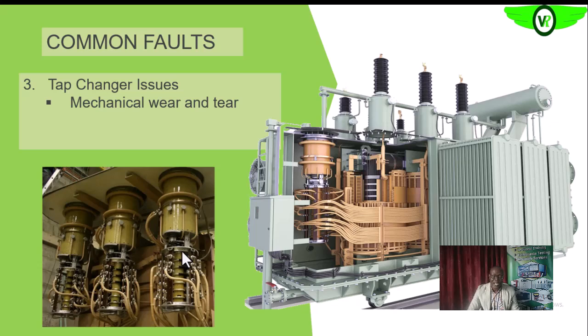wear and tear on those mechanical contacts, okay, that will result in arcing or burning of those mechanical contacts. So there are times too, remember, that the tap changer is an off-load tap changer, which means we may have a system that will help us change the tap while the equipment is off-load. Okay, in most cases we have a motorized system attached to the end of the tap changer that helps assist us in changing the tap.